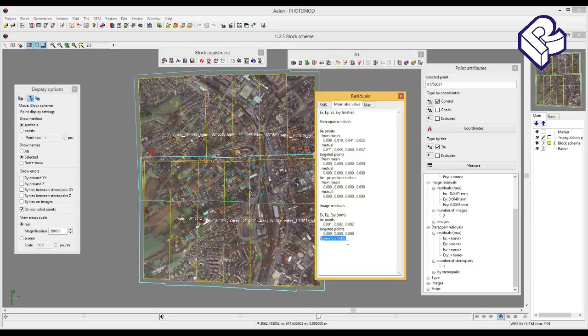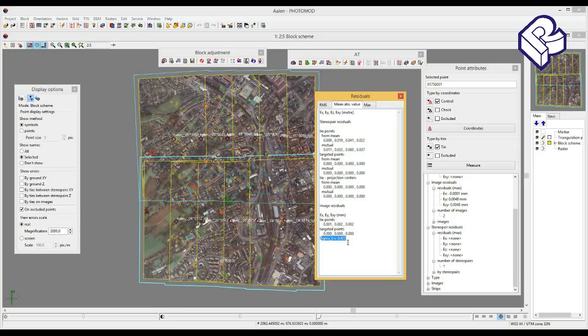If sigma exceeds value 1 significantly, it indicates errors in points coordinate measurements and shows that a priori accuracies of GCPs and projection centers are overestimated. If sigma is significantly less than 1, it demonstrates that a priori accuracies of GCPs and projection centers are underestimated. If you increase values of accuracy for exterior orientation data, it's possible to achieve better values of adjustment accuracy.